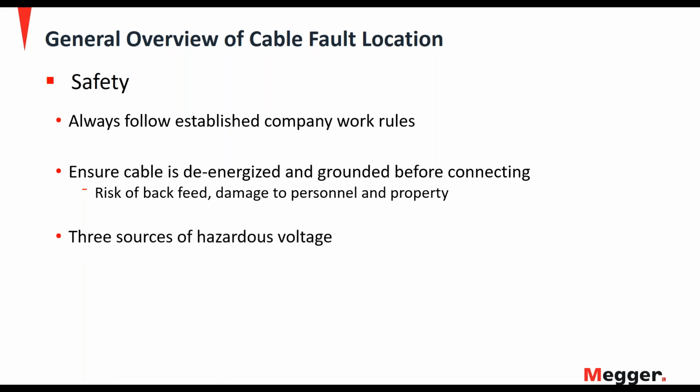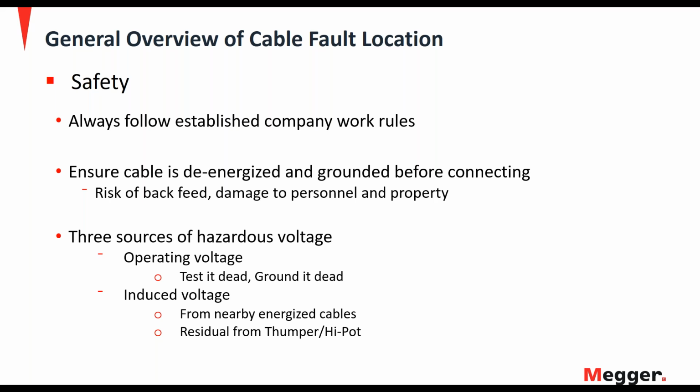While you're working with a thumper out in the field, there's three sources of hazardous voltage that you need to consider. Obviously, there's operating voltage, and you'll have gone through the appropriate test at dead, ground at dead procedure. Because you're working on a cable, you could have induced voltage from nearby energized cables. You could also, if it was a good cable, you might have residual voltage on the cable from the work you did with your thumper or high pot. In other words, you may have charged up that cable.